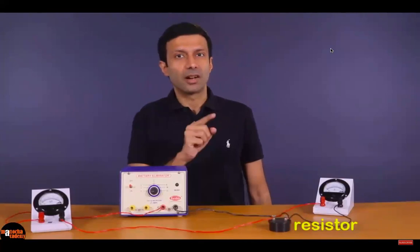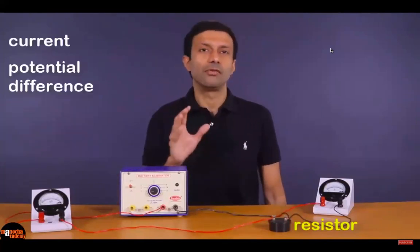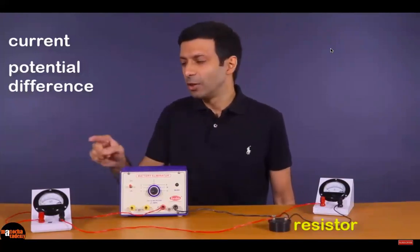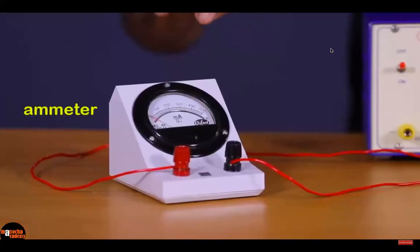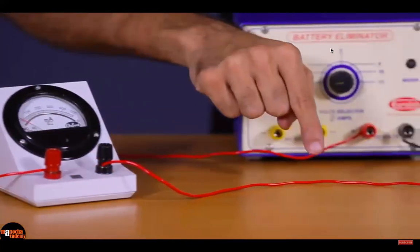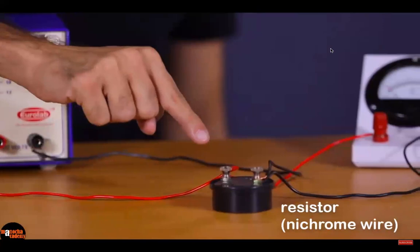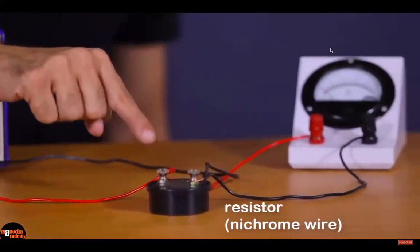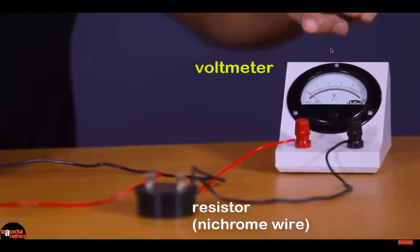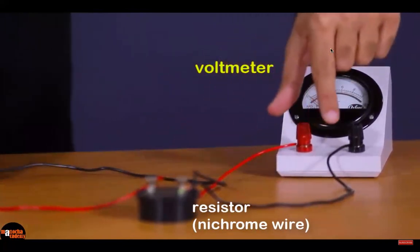We are going to measure the current passing through the wire in the black box and the potential difference across the wire. To measure the current through the wire, we will use this ammeter. The ammeter is connected in series with the wire in the black box. To measure the potential difference across the wire, we will use this instrument called the voltmeter. As you can see, it is connected in parallel to the wire.